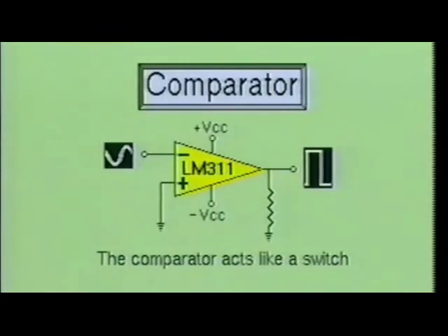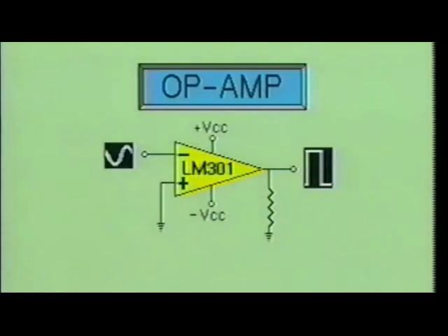We have also seen that the comparator is a linear circuit which has a digital output. Even though the comparator closely resembles the operational amplifier, it is designed to give an output that is either high or low, but never linear with respect to the input. Oftentimes, an operational amplifier with no feedback resistor will function as an acceptable comparator circuit.